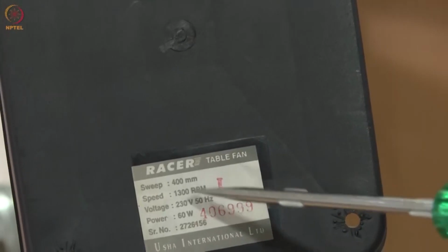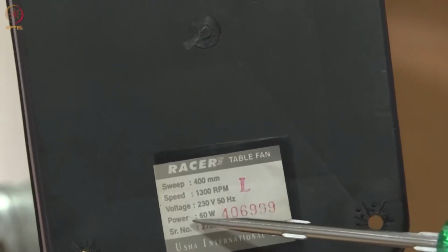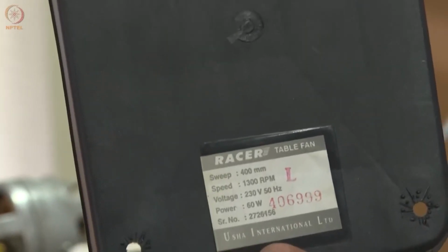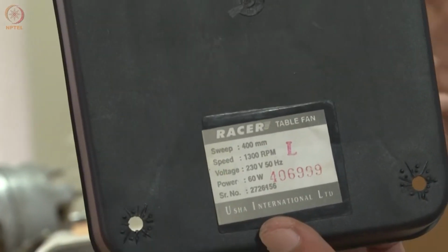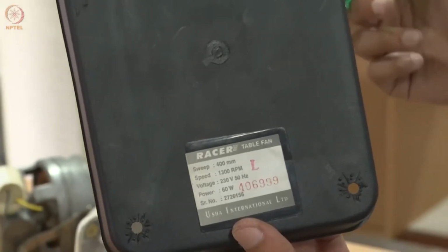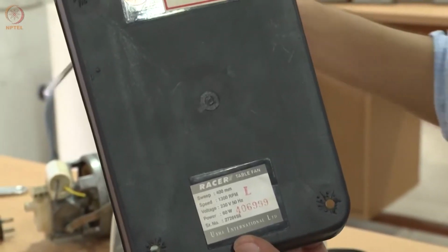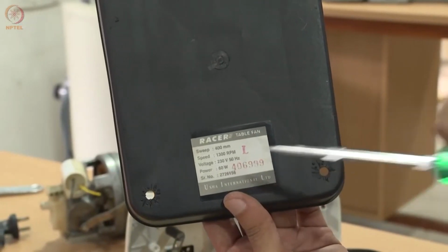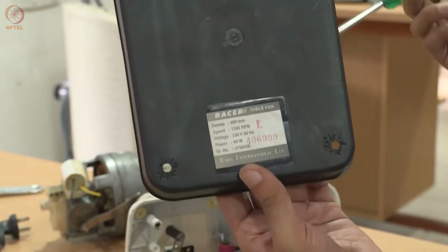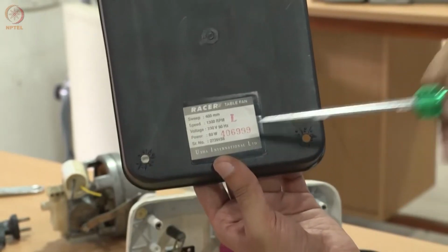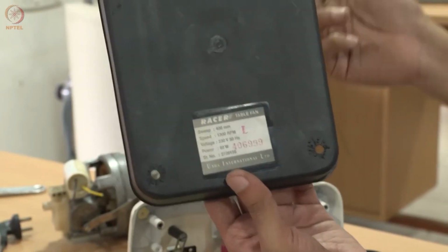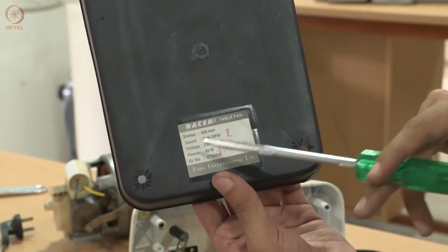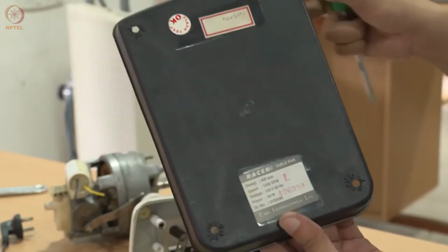The key thing to mind is, please pay attention to the power rating of this motor. So this is 60 watts. For instance, if you look at an electric drill, it will be much higher. It will be 500 watts. It will be 1000 watts. The reason is, an electric drill does more work than a fan which simply moves air. Also, you should pay attention to the operating voltage and frequency, because in India our grid runs at 50 hertz and the standard voltage is somewhere between 210 to 230 volts. Different countries will have different voltage and frequency ratings.